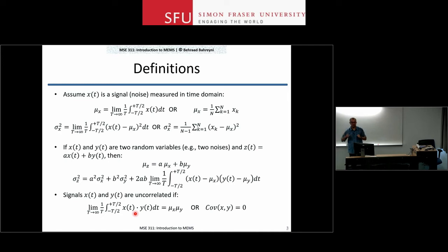The mean of that noise is going to be 0, and I get the covariance that is 0, right? So if they're uncorrelated, I just get the means out, right? All those small changes are going to be 0. The covariance is going to be this integral here. That is going to go to 0 if the two signals are uncorrelated.